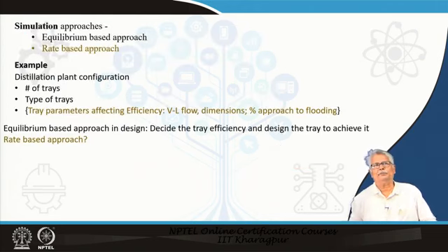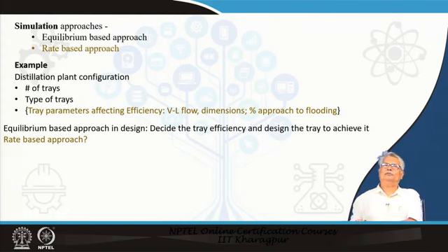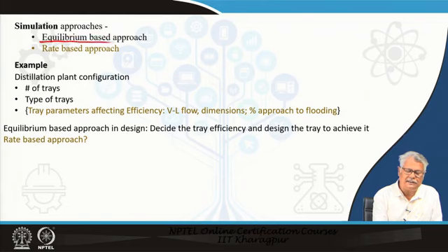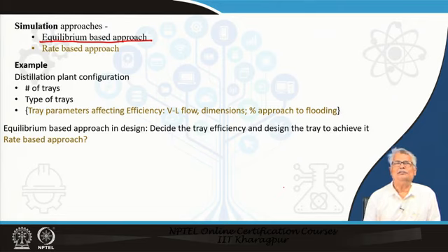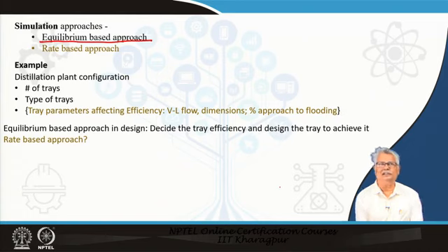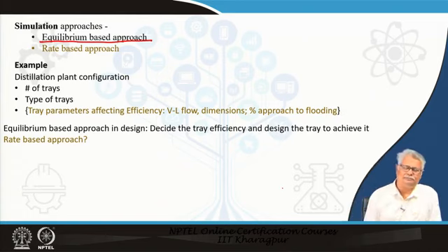So, basically the simulation that I have talked about so far, and the design as well, has been based on the equilibrium based approach. We assumed that every stage will be in equilibrium, thermal as well as mass transfer equilibrium. Then we account for the inefficiency by introducing the term efficiency, and then we arrive at a design. There is another approach which is called the rate based approach. We will discuss this immediately after this.